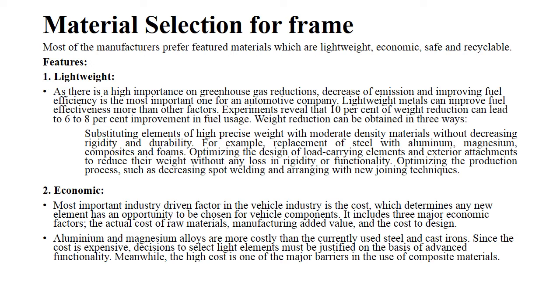Second is the economic factor. Almost all industries are driven by the economic factor, which is cost. We have to make sure that the cost of raw materials, manufacturing, and design is as low as possible. In terms of price per kg, aluminium and magnesium are more costly compared to steel and cast irons. So you need to make sure that the material is not very costly.